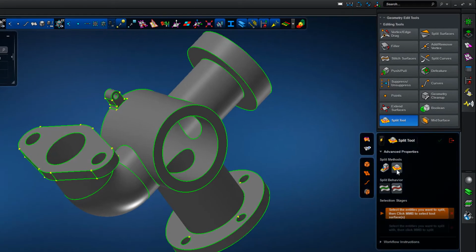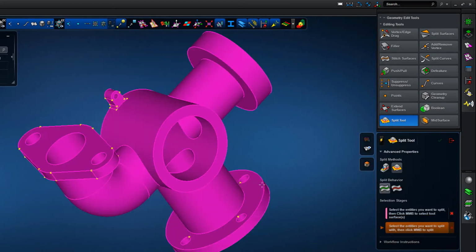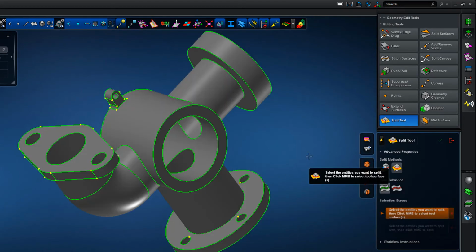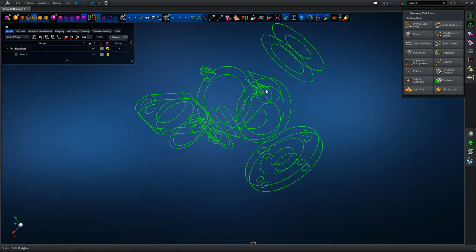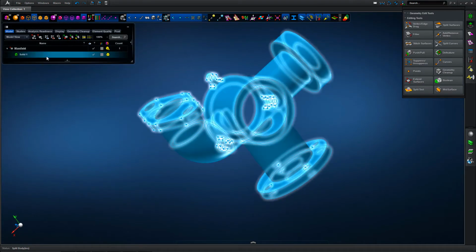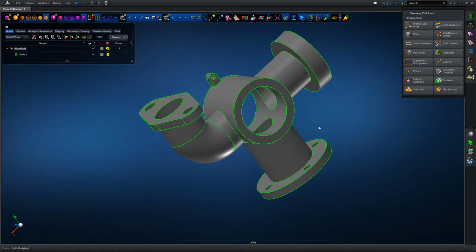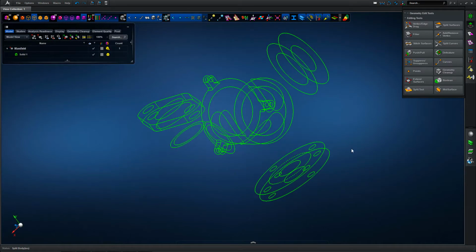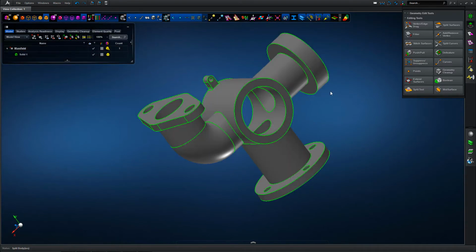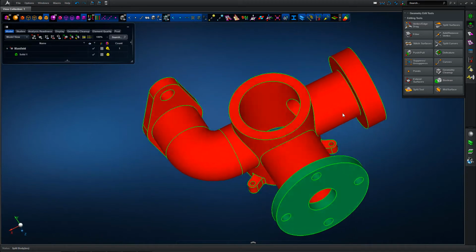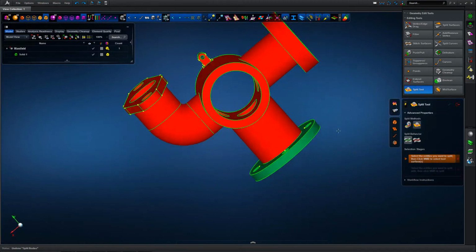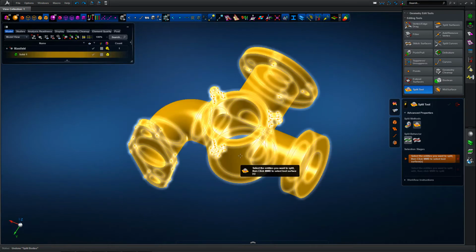What we want to do is partition the solid geometry so that we have a single solid, but with a number of partitions within there, which can be used for discrete hex meshing with a common congruent boundary at the interface between the partitions. You can see if we turn the geometry topology lines on, we can see how the split has occurred. We've still got a single solid within the browser tree, and if we turn the 2.5D coloured display on, we can see we now have the makings of a green region which can be hex meshed.